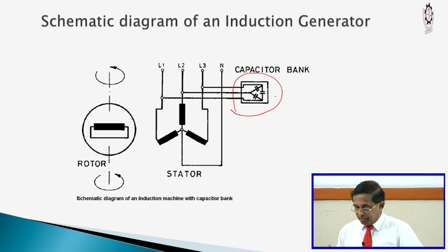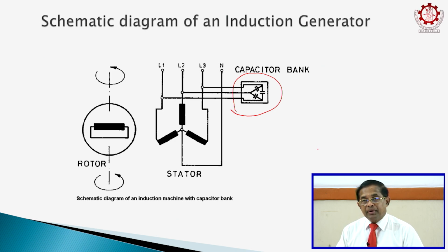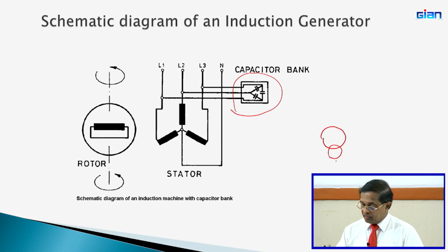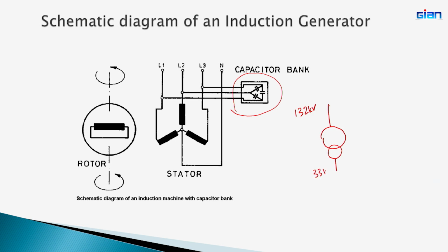So, I will show you a typical arrangement here, right. If you take a typical grid substation, maybe even in India. Say the incoming voltage is 132 kV, usually it is stepped down, for example, into 33 kV as the primary distribution, right. There may be 2 transformers.